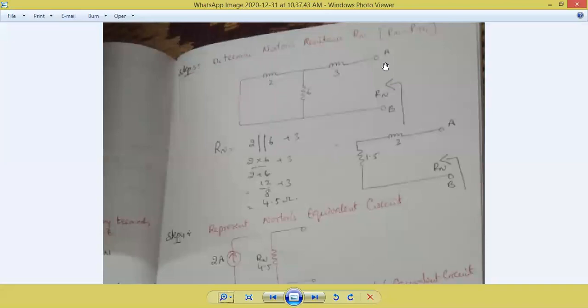So now you see all of you. If I'm watching the circuit from these terminals, what is the assumption? How are these three elements connected? Whether they are connected in parallel or series, we have to check. So first, if I'm watching the circuit from A and B, I have to reduce the circuit from the opposite end, as I mentioned yesterday. So at the opposite end, which resistor are you having first? Anyone tell me? 2 ohms. And next which resistor are we having? 6 ohms. Okay.